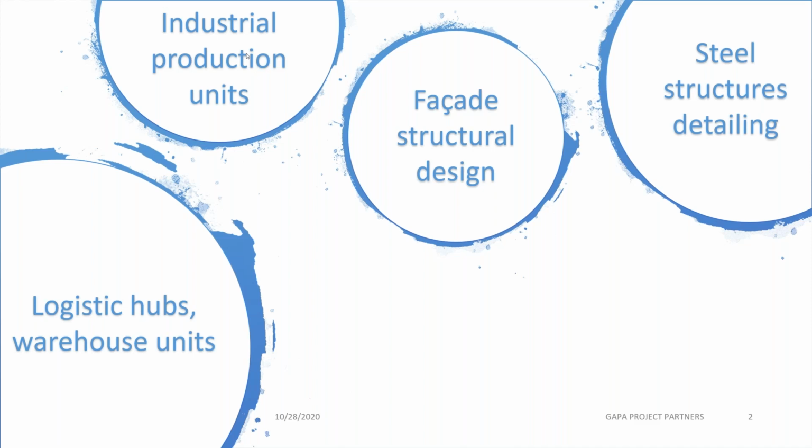Most of our projects are based in Romania or the neighboring countries. Those based in Romania also have to satisfy seismic design requirements, as Romania is a seismic country. On these projects, our design scope generally includes all the elements that form the objectives. So this includes the main precast structure, the secondary steel structure supporting the facade and roof, the roof metal sheeting, the ground supported slab, annex structures, and so on.